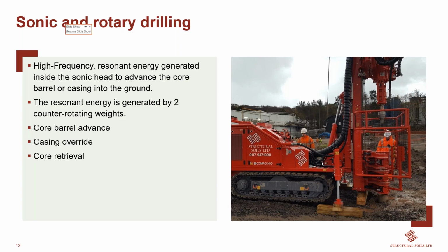It works extremely well. It is more expensive than standard rotary, but if you've got a large site with a number of different holes on it, this again would be the perfect tool for the job. So once we get through the overburden and hit the rock, we can just change the sonic head for the rotary head, and then carry on with the rotary head. That means that we've got one setup on site, and it's a lot quicker for our client. So obviously it will be cost effective.